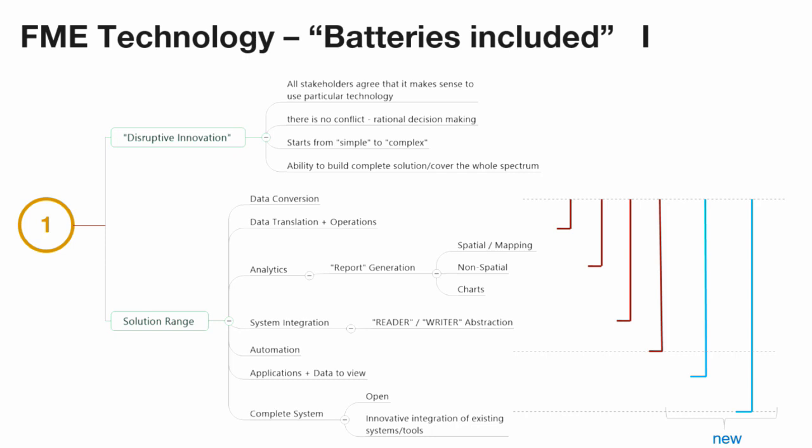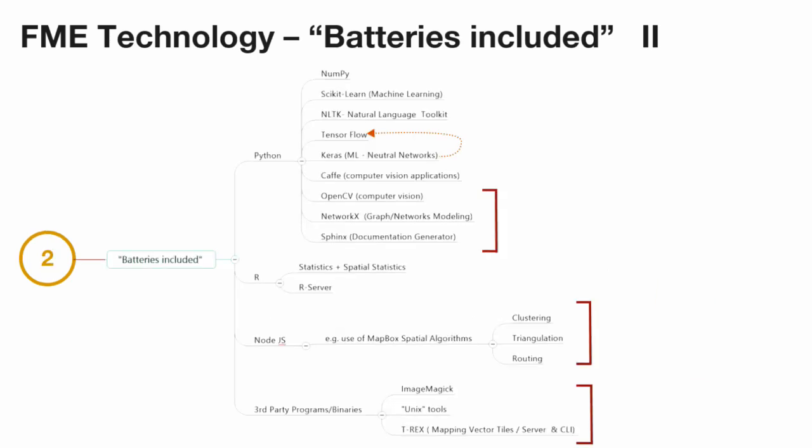So as I said, we started out simple, just doing simple data conversions. I want to take this little piece of text from this layer in the AutoCAD drawing. I want to take the polylines from assignable floor space and bring them over. As I'm bringing them over, I want to make sure they're closed polygons. If they're not closed, use these algorithms to close them. As I'm putting them into GIS, concatenate that room number with the building number and the floor code and the drawing, and put it into Esri format. So that's kind of how we started. Now we use it for all kinds of different systems, which is what I'm going to get into as we go on.